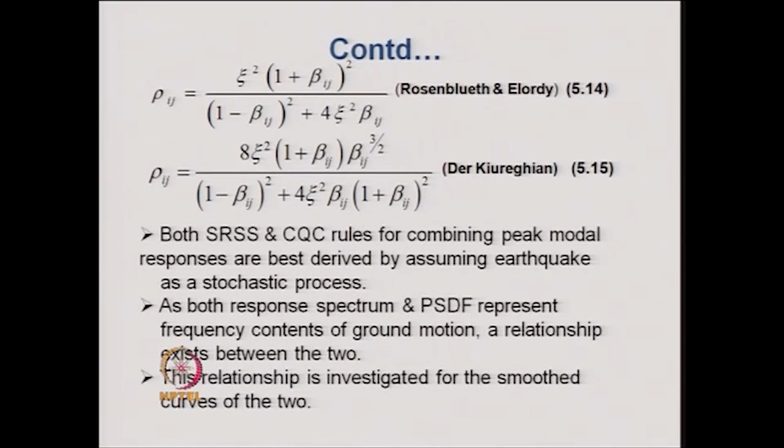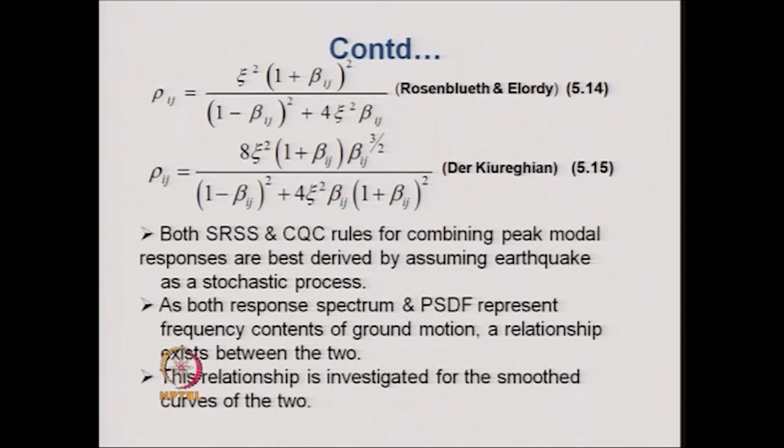So, that is a thing that one should take note of, because the response spectrum of any earthquake is nothing but the maximum value of the displacement response plotted against time period, or it could be plotted against the frequency, and from that one can obtain the response spectrum for acceleration simply by multiplying the response spectrum for displacement with omega square.